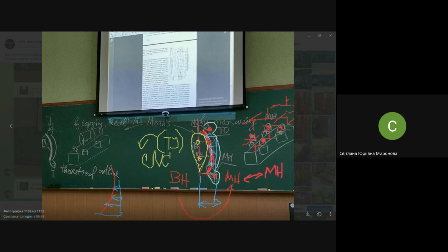With the appearing of computers, they have got other names. There is no need any longer for templates, for instance, but the idea was the same. Measure position of the contour with respect to the intermediate element in the locator, this mounting hole. Measure position of the system of mounting holes in a jig frame, in a jig skeleton, and combine one mounting hole with another mounting hole.